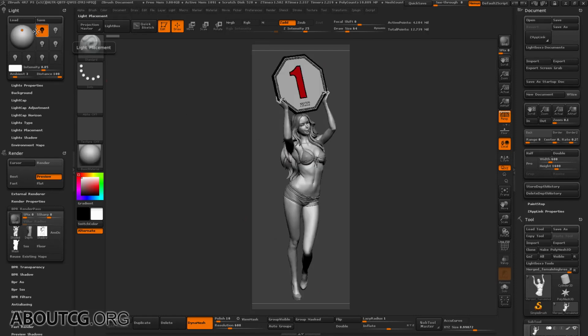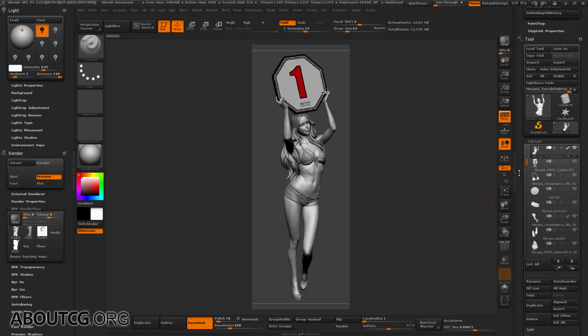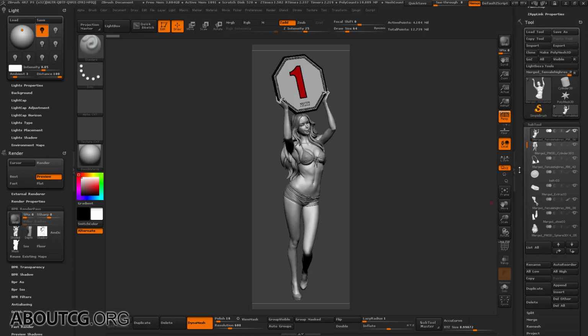When we render the ID mask, we need to set the material to flat color. So everyone can see it here. Our character is displayed without lighting. At this point, we don't need these vertex colors on its face, including the vertex color on this board. Remove it.